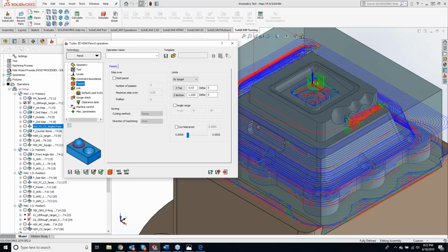I know it's pretty vague just because it all depends on what machine you guys are using, but I wanted to give you the information so you can go back to your machines and say, well, I was running iMachining and it was stuttering a little bit, so now I know I can come in there and change it and play with that number.